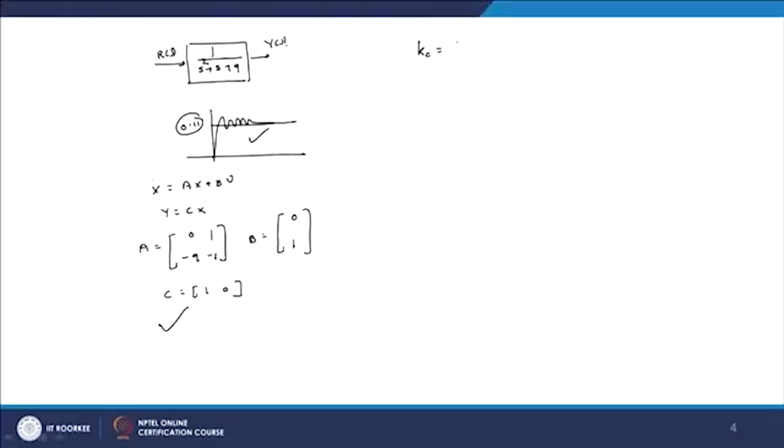So here the controller Kc is given as 0 1, then the controllability matrix inverse, times phi of A. Phi of A is formed with the desired poles. So here our desired poles are at, say, minus 1 and minus 2. Now Kc is given as 0 1, and here B, AB inverse, and here this phi of A.